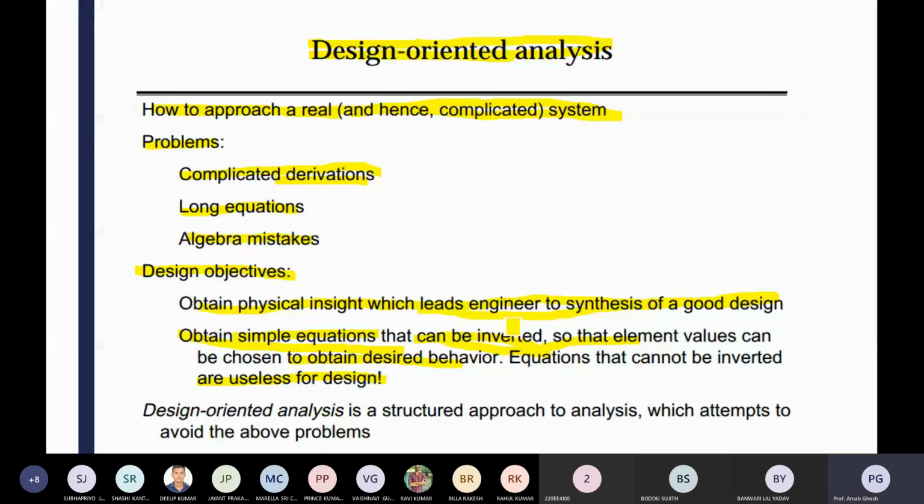So your transfer function is not proper, and you have to make it proper. That's why we include 1 pole in the denominator, called the low pass pole. That pole is normally developed for a low pass filter, which you include additionally to stabilize your PID controller.